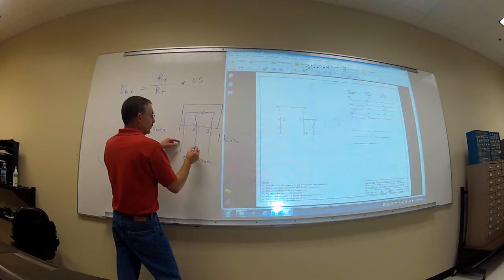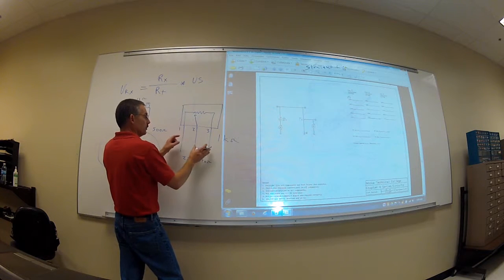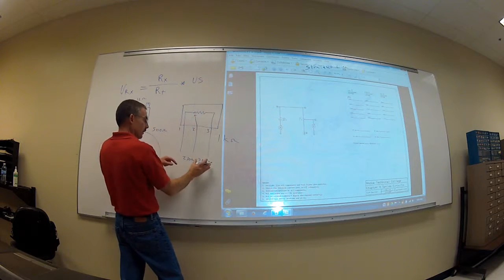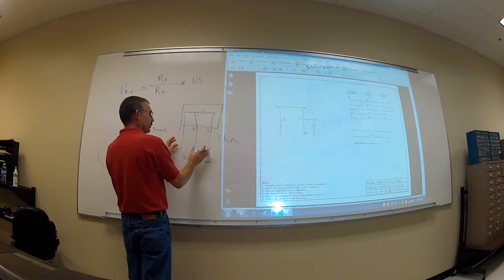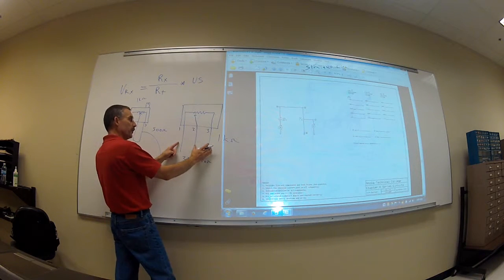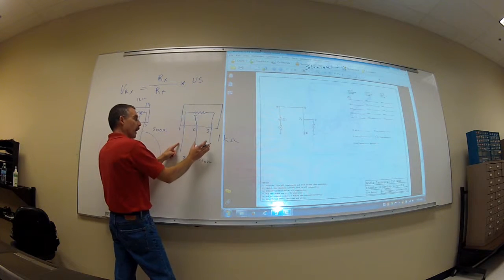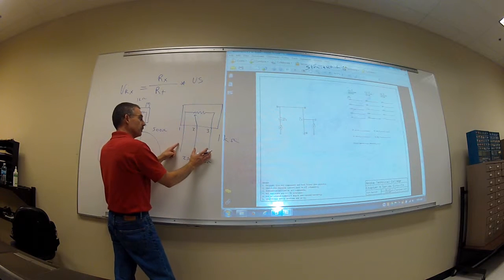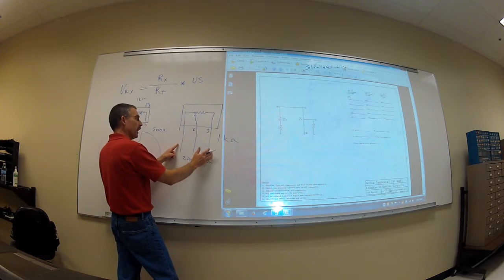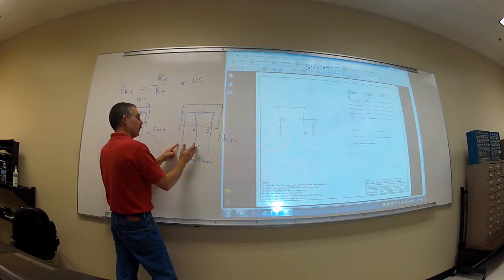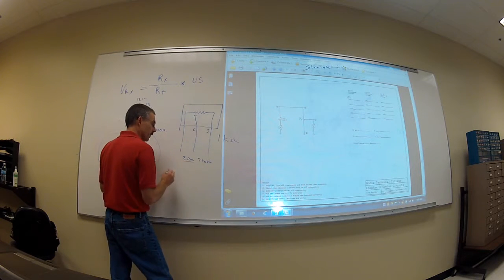So when I had that jumper in there, if I jumper off pins 2 and 3, I'm basically shorting out this 750 ohms. So when I measure across pins 1 and 3 with the jumper in there, I'm only going to measure 250 ohms. I pull it out of my breadboard and leave the jumper in there and go across pins 1 and 3, I'm going to measure 1K. And if I go across pins 1 and 2, then I should measure the correct things.